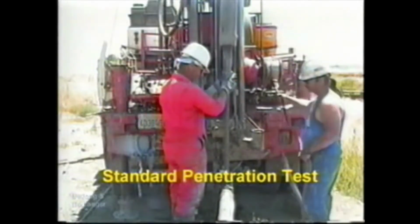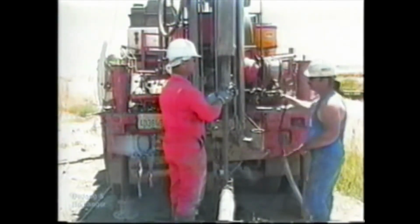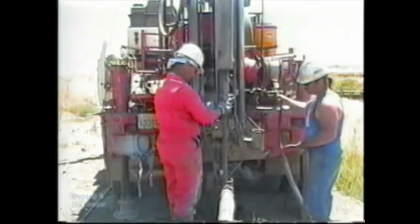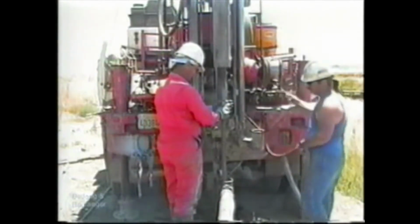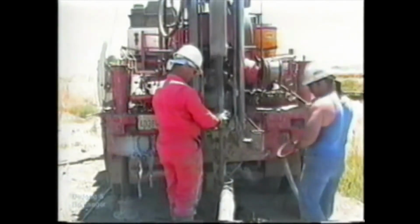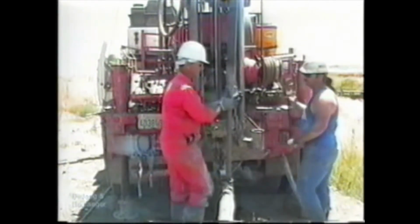A relatively simple and standardized method for estimating the compactness or stiffness of the soil in situ is the Standard Penetration Test, or SPT. This test consists of counting the number of blows of the hammer required to drive the split spoon sampler a specified distance into the ground. The essential features of the SPT test include a drop hammer weighing 140 pounds, falling through a height of 30 inches onto an anvil at the top of the drill rods, and a split spoon having an external diameter of 2 inches and an internal diameter of 1 3/8 inches, and a length between 18 and 30 inches.